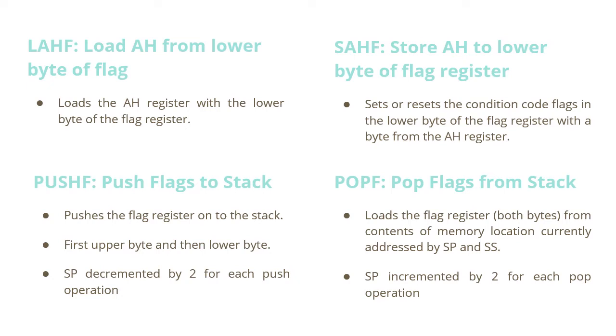Next is the POPF operation, which means pop flags from stack. Here what happens is that it will load the flag register, that is both bytes of the flag register, with the contents of the memory location that is currently pointed to by the stack segment and the stack pointer. The stack pointer is incremented by a value of 2 for each pop operation.